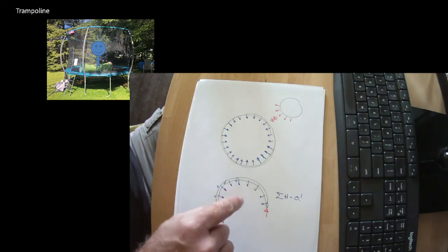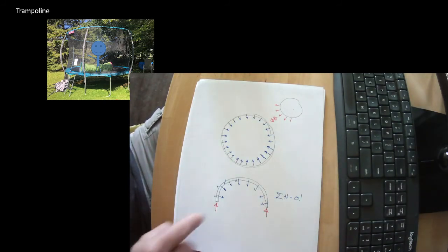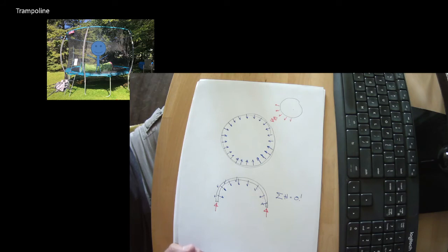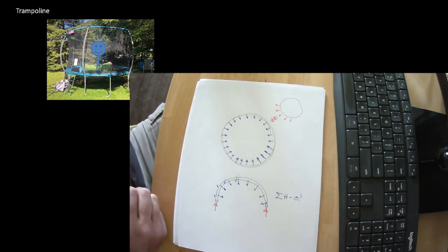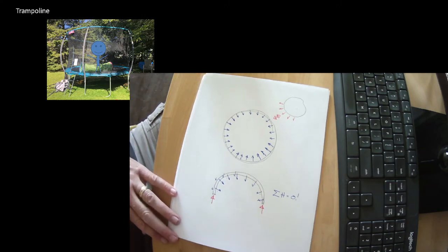This is a beautiful thing because this says that the boundary of our trampoline, notwithstanding that these are very, very large forces, is in equilibrium with no bending on it. Which means that this is just a simple compression ring. This is a variation of what's called the boiler problem. And the boiler problem is how much force is in the wall of a boiler.